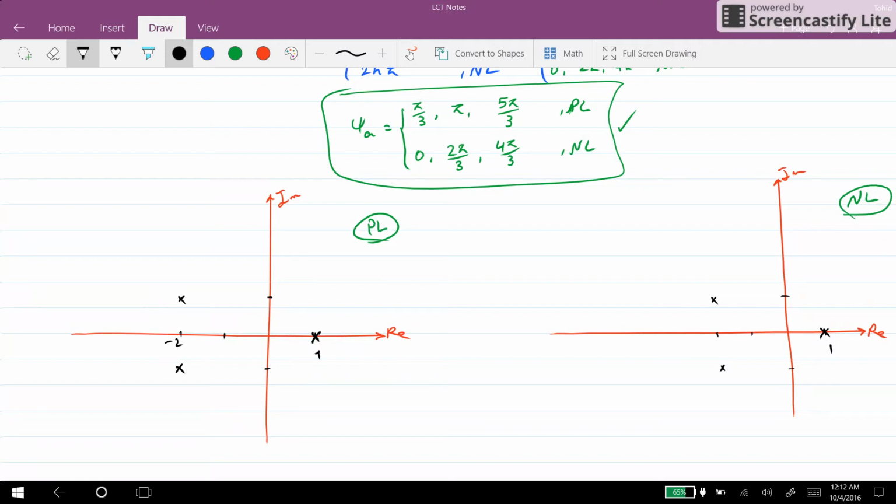So now we can start to draw the asymptotes. The point of abscissa is at (-1, 0). For the positive locus, we have asymptotes with angles of pi over 3, pi, and 5 pi over 3. So if I draw the asymptotes, we will have these asymptotes, as you can see here. These are the asymptotes that we have for the positive locus.